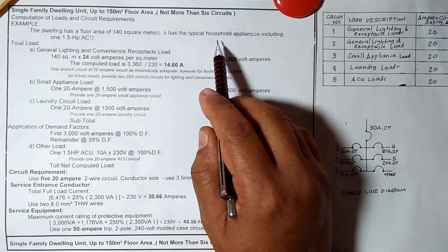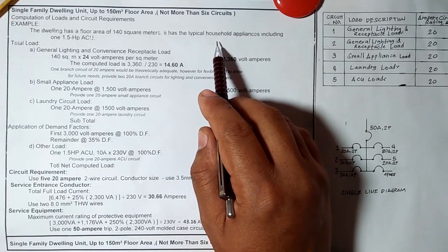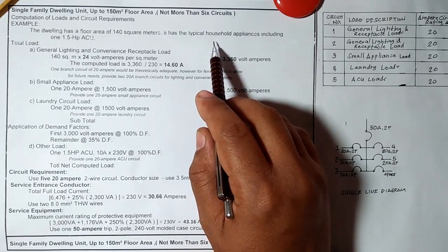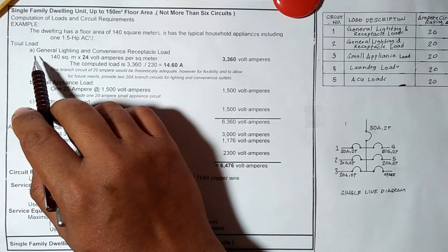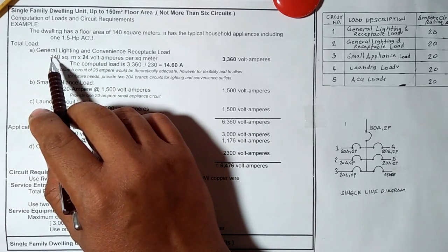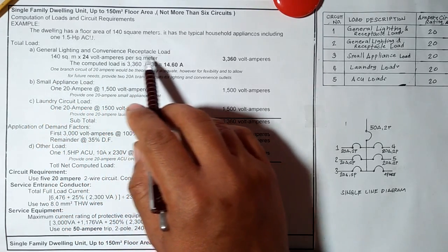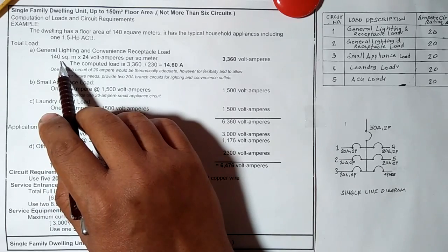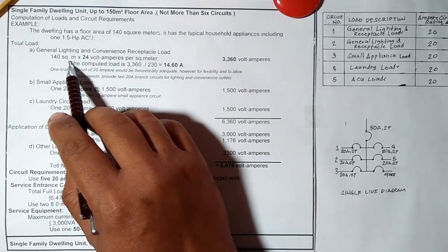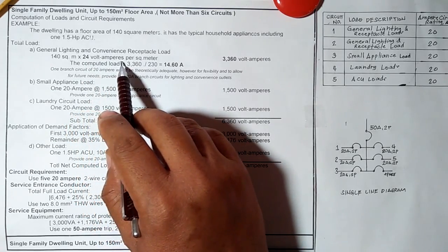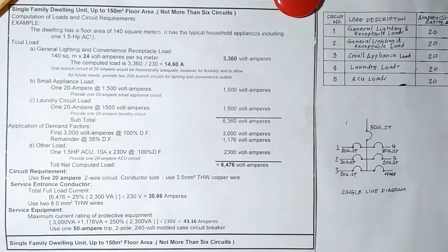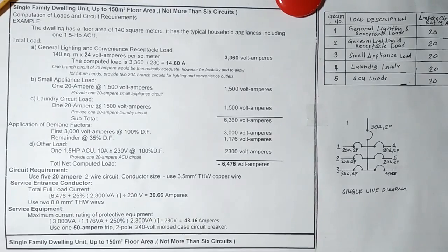So in here we will again create general purpose branch circuits. To get the total load, letter A, general lighting and convenience receptacle load: 140 square meters times 24 volt amperes per square meter, as we discussed last time,